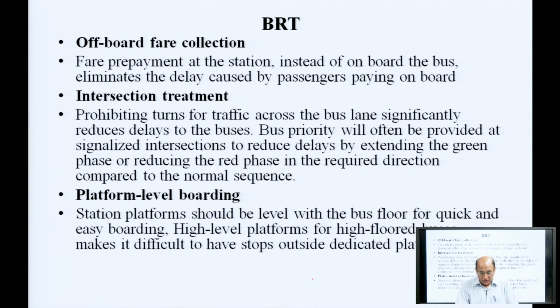Bus priority will often be provided at signalized intersections to reduce delay by extending the green phase or reducing the red phase in the required direction compared to the normal sequence. Platform level boarding. A station platform should be level with the bus floor for quick and easy boarding. High level platforms for high-floored buses make it difficult to have a stop outside dedicated platforms.